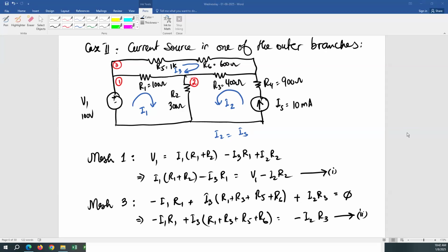If you want to find the voltage across R4 and calculate the power using that voltage, then it's going to be the power consumed in R4. The current times the voltage drop across. No, that's what he said. But that's incorrect though, because if you use the voltage across R4, that means you're calculating the power in R4, right? Consumed in R4.